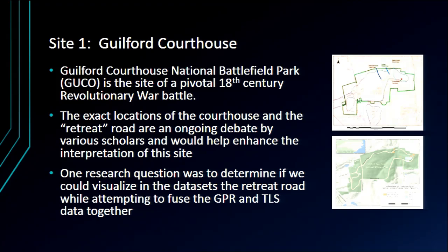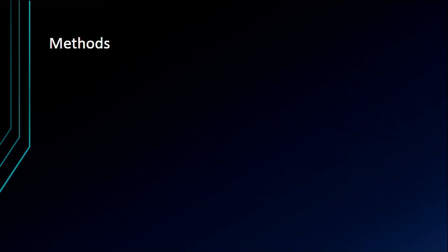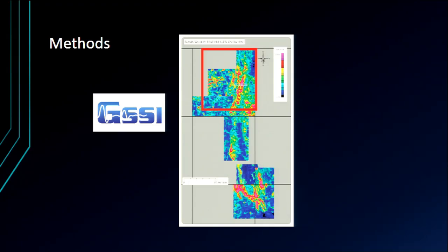So on the surface of it, what we wanted to look at is the GPR data. That's how we found this whole thing. We found the subsurface using GPR, and then it disappears down into the woods. GPR sends a radio wave down into the ground. Any change within that ground surface will get recorded. So if all the surface is the same going down, you don't see any change. If you hit change, it gives you a reading. So we found the whole road. We mapped it out. It runs right down through here and out with the GPR into the woods.